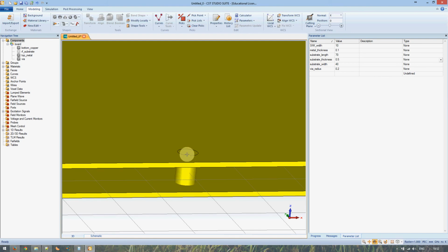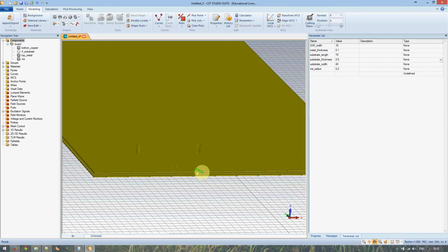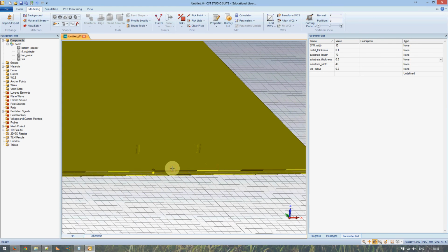Now, I usually leave the inner radius as 0 to make the CST simulators a solid cylinder of copper. Because of the skin effect and other things, this doesn't really make a difference, even though wires are usually just holes that have plated metal on the inside of them. So they would only have a very thin piece of metal, and on the inside would actually be air. But for the purposes of simulation, that very seldom makes a difference.